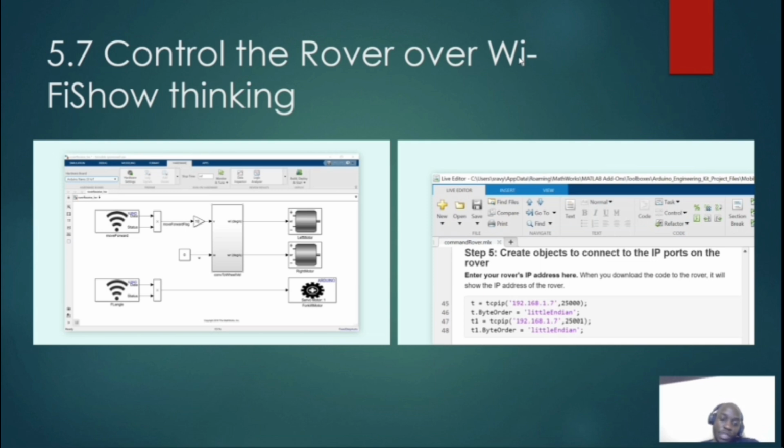So, in summary, the Stateflow chart decides the desired overall movement based on the fused localization, and the PI controllers calculate the necessary linear and angular velocity using kinematics, and convert these to individual wheel speeds. Finally, the speeds are translated into PWM signals to send to the motor drivers to make the robot move. I'll give it to my classmate so that he can further elaborate.